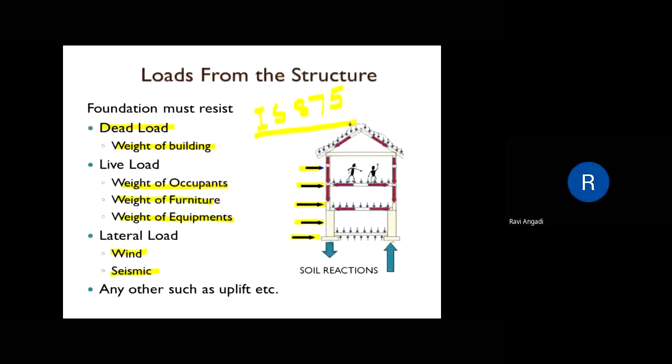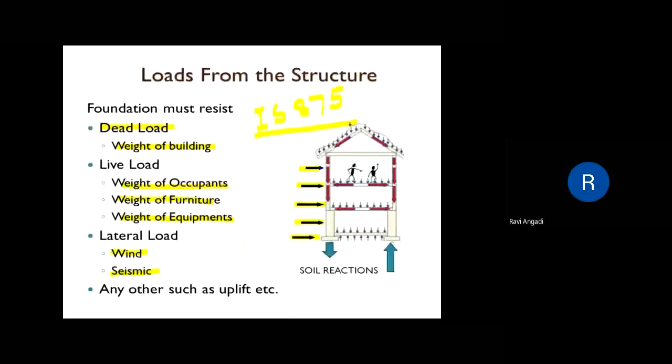Then comes the seismic. Again, the force due to an earthquake may act vertically, laterally, or torsionally on a structure in any direction. The worst condition should be anticipated, and the relevant code is consulted for the design of the foundation.